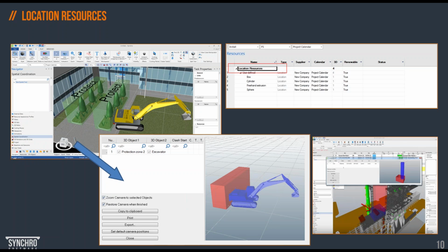We can also clash detect working range from the crane with some other workspaces. We can highlight pedestrian and vehicle routes, project phasing, that's another example. Also simulate different types of work or disciplines, different trades within specific defined space rather than simulating the objects from the model. That's also possible, and that's very useful for crew coordination, if you like.